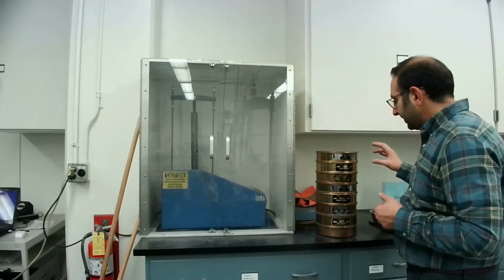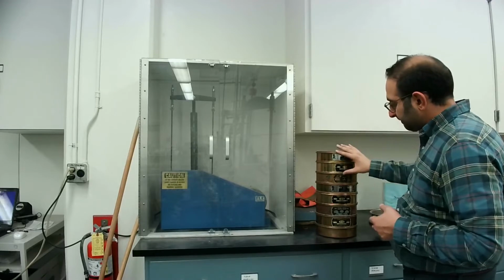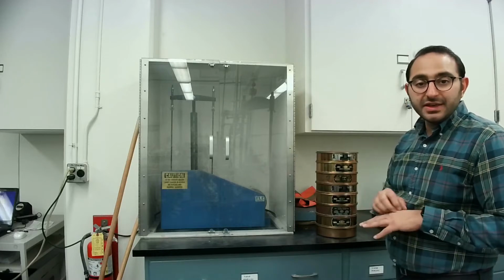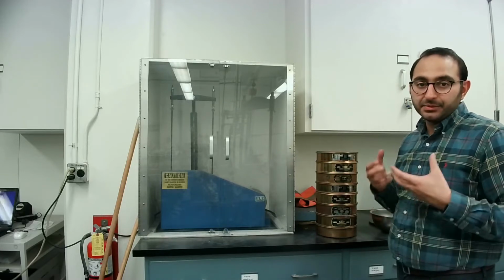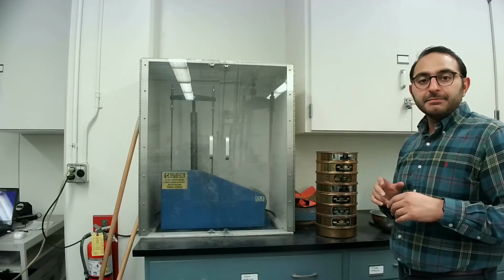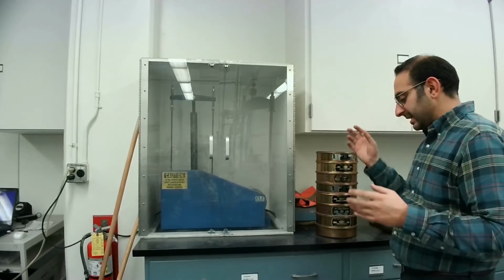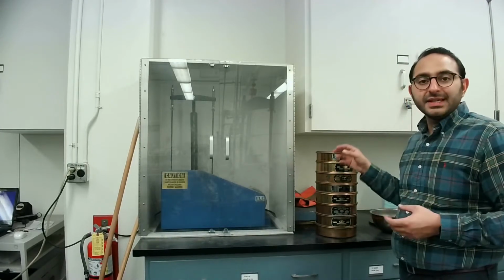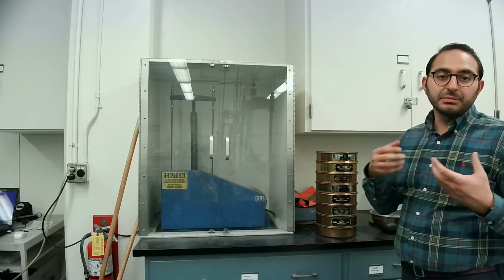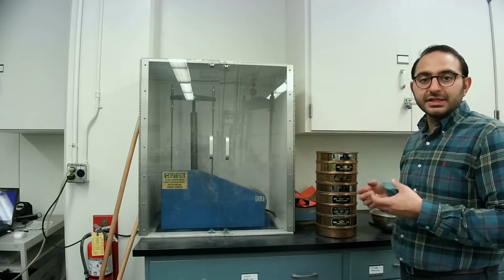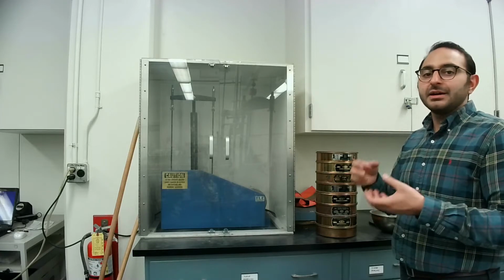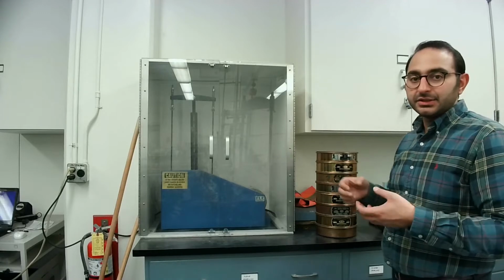But right now the idea mainly is to grab these sieves and make sure that they're clean, weigh them. We have to weigh the sieves before we run the test. So basically an empty sieve, because as we start shaking the shaker, what's going to happen is that a little bit of soil is going to be retained on each one of the sieves. So if we have the weight of the empty sieve before shaking it, and then we have the weight of the sieve after shaking it with the amount of soil that's retained on top of it, that is how we will be able to construct our grain size distribution curve.